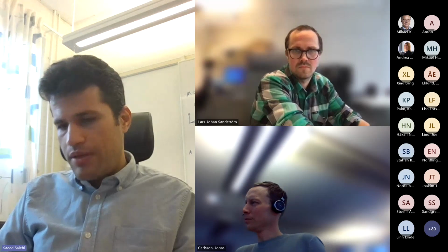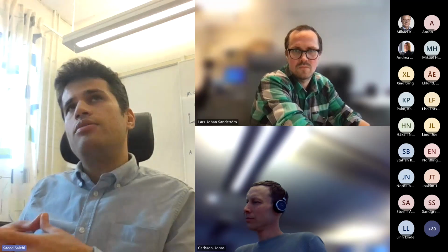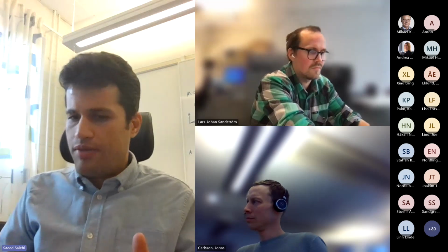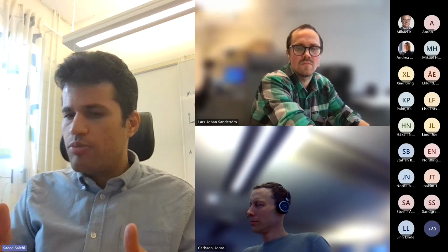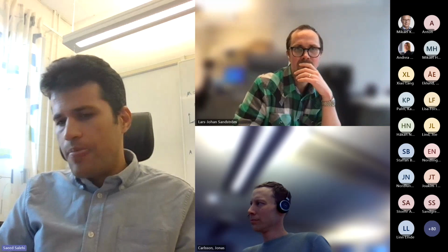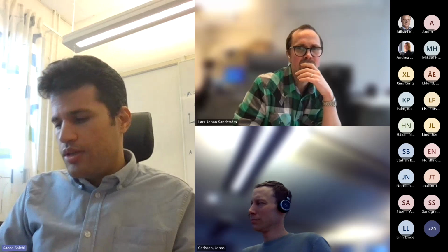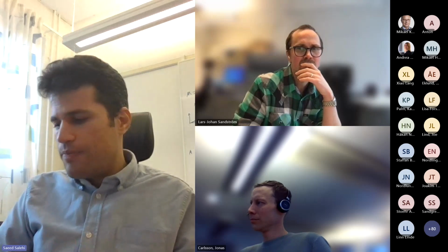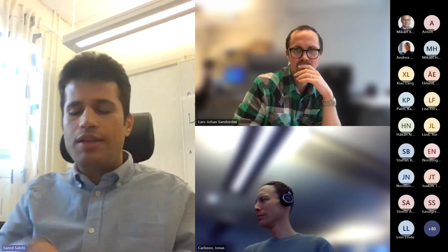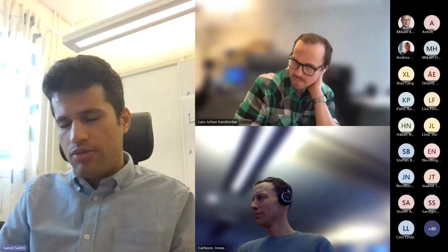Yeah. So here my main focus is on the deep reinforcement learning mechanism itself. So the actuator could be anything. Could be a jet, could be a pulsating jet, could be an axial jet, could be any kind of additional geometry that is actively controlled, like blades or guide vanes or anything. But that could be anything, and the model will be able to train that actuator in an efficient way to control the flow.